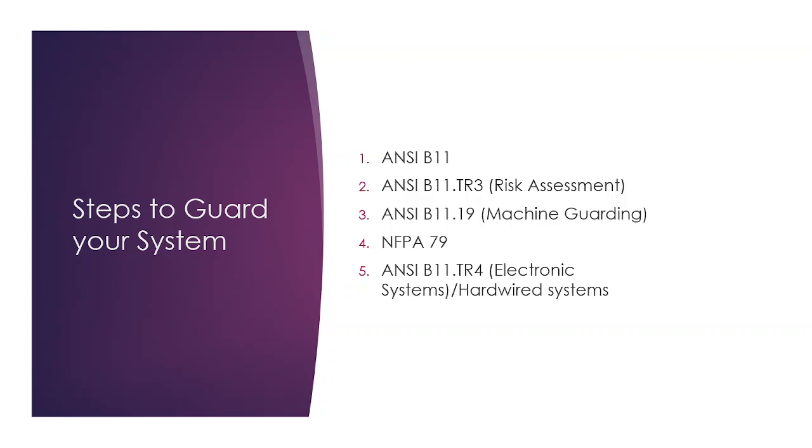This standard more or less gives you the breakdown to understand why we use that type of controller, what the benefit is, what the breakdown of the actual controller itself is, and why it needs to be a safety rated controller versus any other standard PLC. Even a dual redundant system isn't quite meeting the standard of a safety controller. So if that's something that you want to understand a little more of, feel free to obtain this standard from the ANSI store.